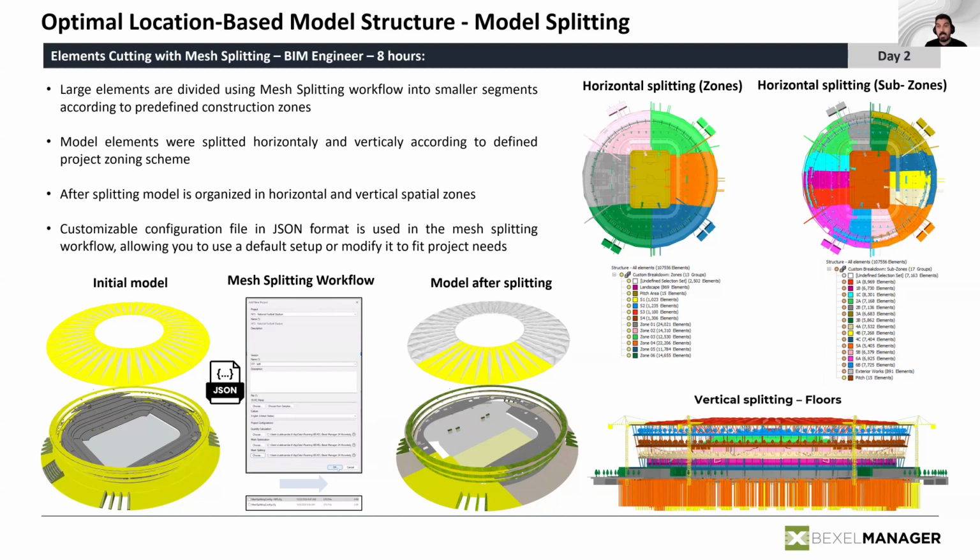That means that we had to take the model as it is, and in a very short period of time, to simply organize it and to change it in order to fit the sequence of execution that is needed. I mean, some practical examples, you get the stadium with the slab, one slab for one floor for the whole project. So you can imagine how it would look if you try to schedule or to track the progress on a stadium like that, with elements of such scale that are going to be built in reality for like 6 months altogether to simply complete one slab.